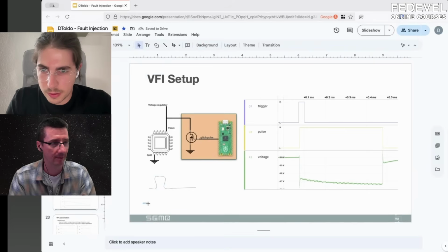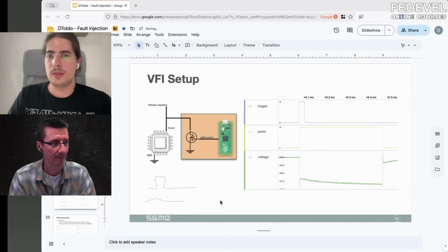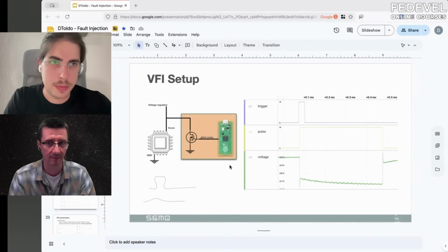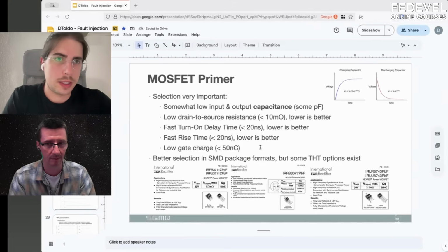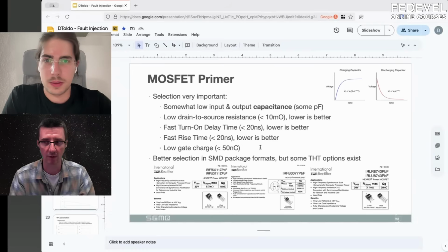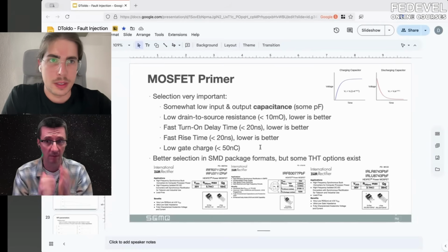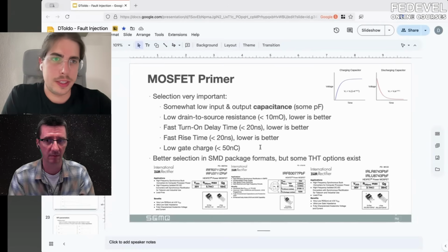And in analog, we get this. So especially with a microcontroller like this, they don't have strong GPIO outputs and they are not fast. So sometimes you even want a gate driver for the MOSFET just to be able to get really, really fast rise times. So you need two transistors, or a gate driver IC maybe.